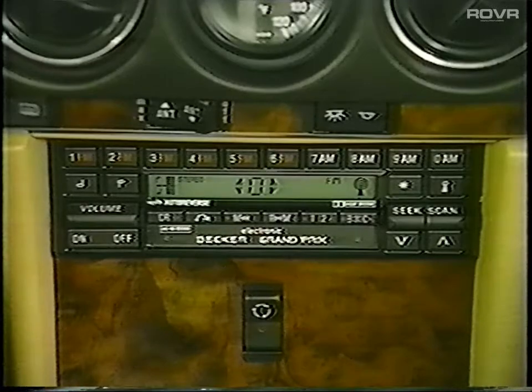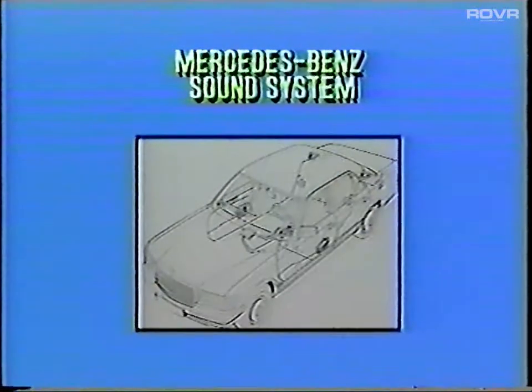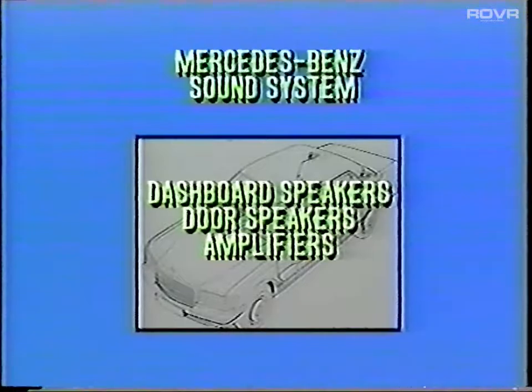Be sure to remember this feature in the event of a customer complaint of no output from the left or right side speakers. The Mercedes-Benz sound system is standard equipment on the SEL and SEC models. This system was developed specifically for the interior acoustics of each model. Therefore, the dashboard speakers, door speakers, and amplifiers on the coupe and the sedan are designed for each model and should not be interchanged.